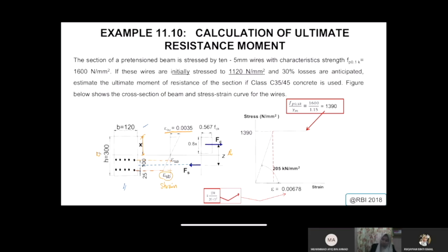Here is the stress. For the stress, we still have 2 conditions, which are the compressive and the tension. The stress block contributed by the concrete we simplify to become rectangular, whereby we have 0.8x here, and the maximum stress of your concrete, which is 0.567 fck.